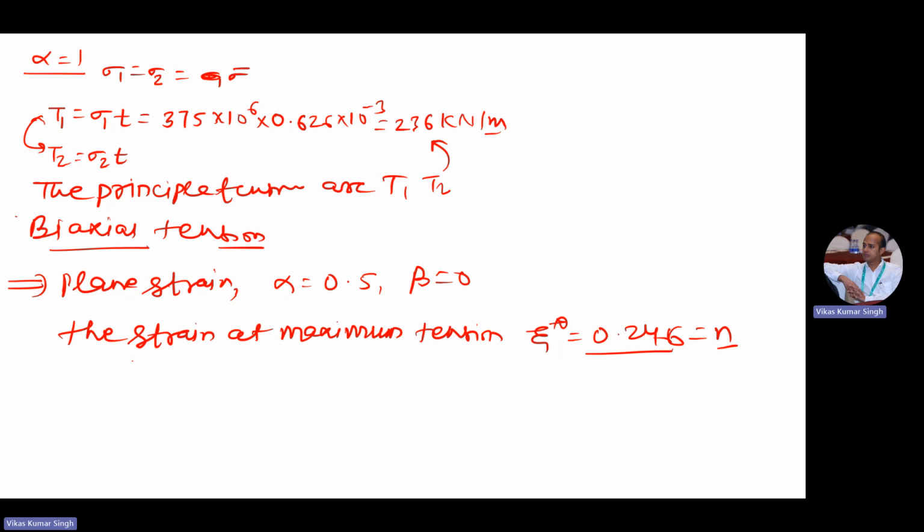it's going to be n in this situation. And then next we have to find out what is the effective strain, and this formula 2 by root 3 already we have long back calculated, going to be 2 by root 3 times of principal strain, say, epsilon 1, and what will be the effective stress, and this is going to be root 3 by 2 times of sigma 1. If we put all this value epsilon 1 and sigma 1, we will get the effective value of the strain and stress. Now the thickness at the maximum tension we can calculate. In the case of all we are calculating is in the case of plane strain now.